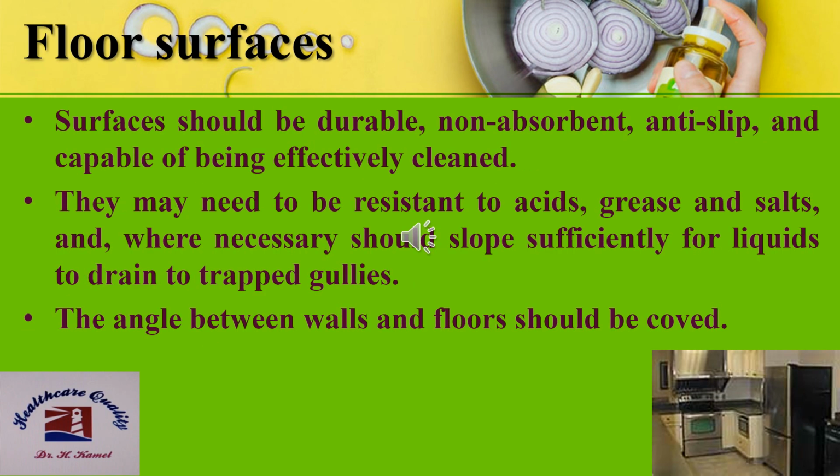Floor surfaces should be durable, non-absorbent, and non-slip, and capable of being effectively cleaned. They may need to be resistant to acids, grease, and salts, and where necessary should slope sufficiently for liquids to drain to trapped gullies. The angle between walls and the floor should be curved.